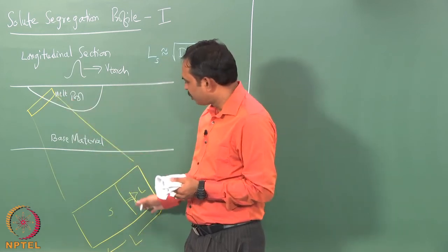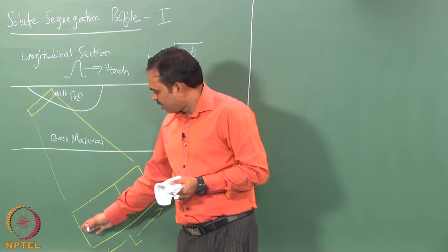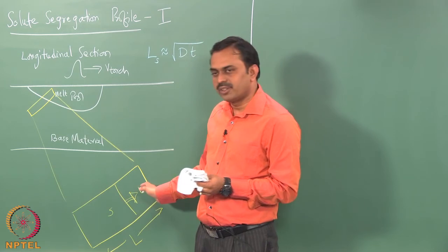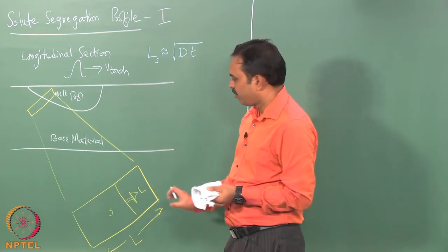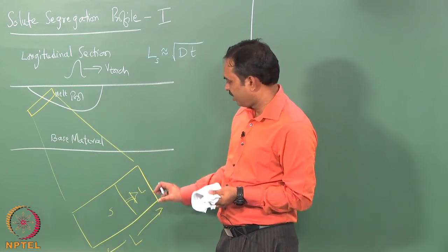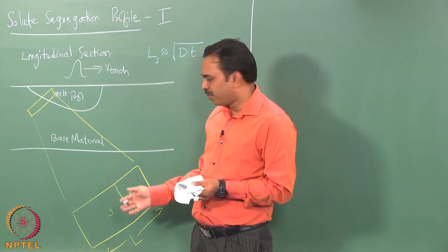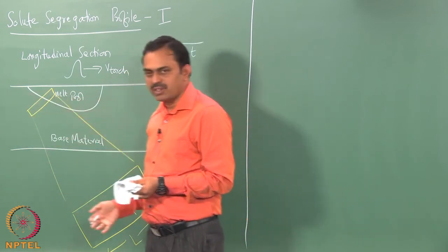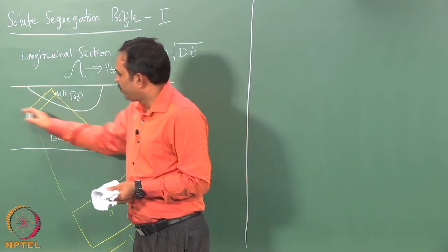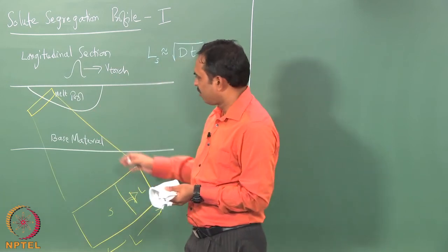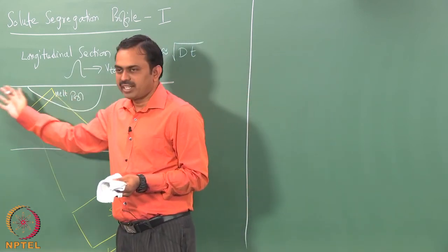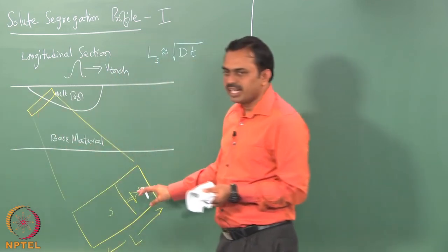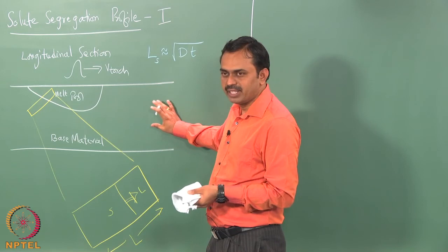I have enlarged it to show you that in this particular small rectangular domain we have almost directional solidification taking place. So, if we can understand the microstructure evolution of the weld pool within this domain, then we can apply it to the rest of the weldment, because we can imagine the solidified weld behind as comprising the stacking of these rectangular domains one after the other. The domain that we are looking at is much smaller than the actual weldment, and this must be kept in mind.